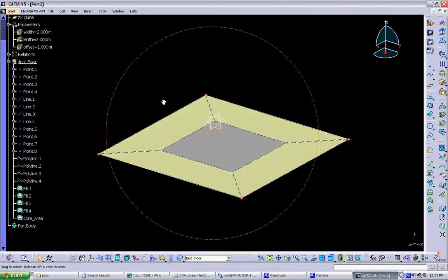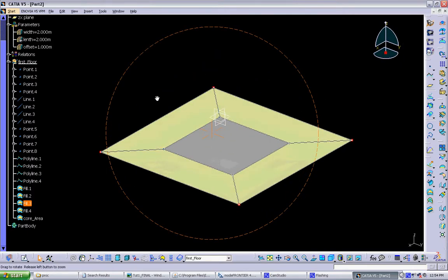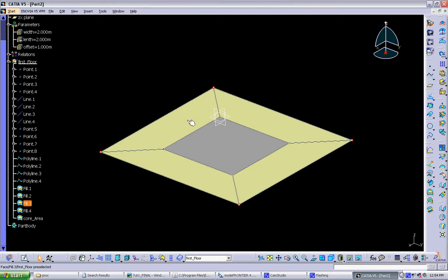Now we want to change this model a little bit, because I want to be able to copy this whole floor instead of rebuilding it again for the second floor. I want to copy the whole object as a group, and just by changing some of the inputs, I can have it move up. So in order to do that, we want to change the object. Instead of this point referencing the XY plane, we're going to build another plane into the object itself that has an offset. Then we can control the height of the floor a lot easier.